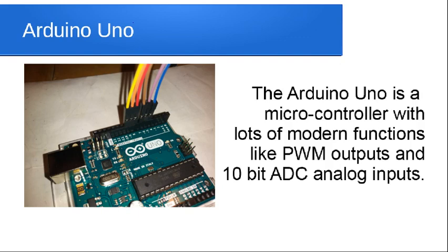Now, your 10-bit, that's not that bad. Think of it this way. You've got a 0 to 5-volt input. You're dividing it by the 10 bits, which is 1,024. So basically your accuracy is 5 divided by 1,024. Not bad if you just want to see something that's basically within a tenth of a volt, you have greater accuracy than that.